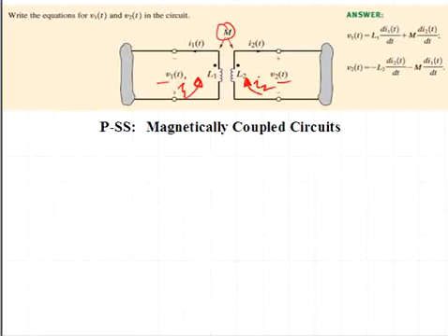We'll notice that the currents I1 and I2 enter the undotted terminals of the two inductors, and this means that the mutual coupling or mutual inductance term will have a positive relationship to those currents and the self-induced voltages across L1 and L2. So we'll consider first the voltage V1(t), and that is induced by the current I1(t) flowing through the inductor L1.